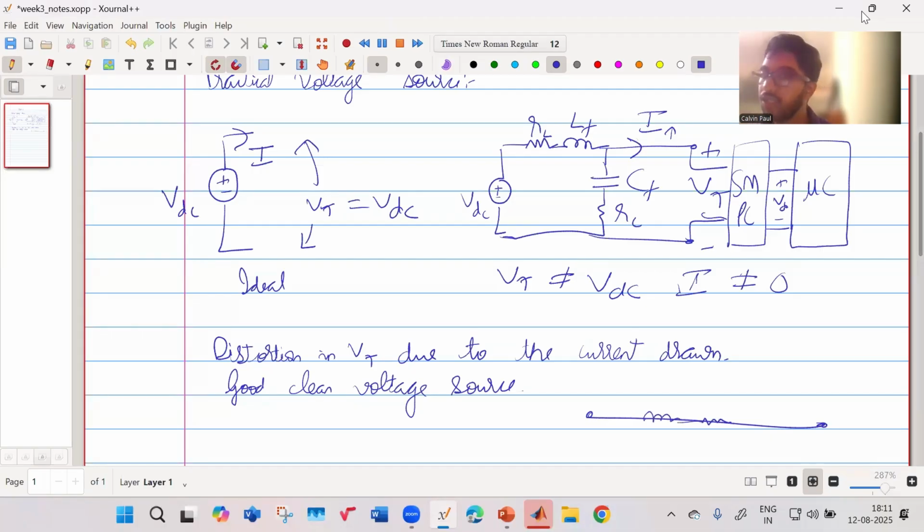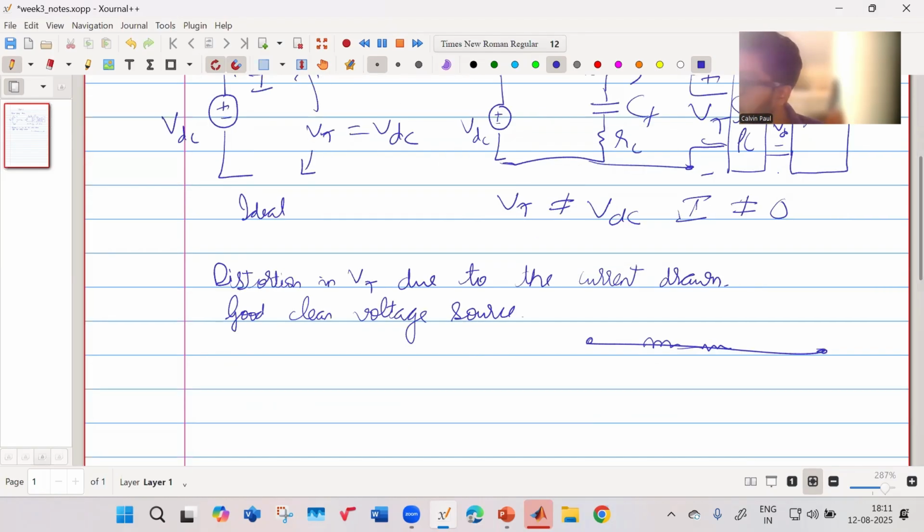So you'll have to reduce that amount. Further, sometimes what they do in PCBs is connect lots of input capacitors. What these input capacitors will do is cancel out this parasitic inductance which is coming up, as well as take off all the ripple current, so that the current which is drawn over here is constant. It is free from the ripple.